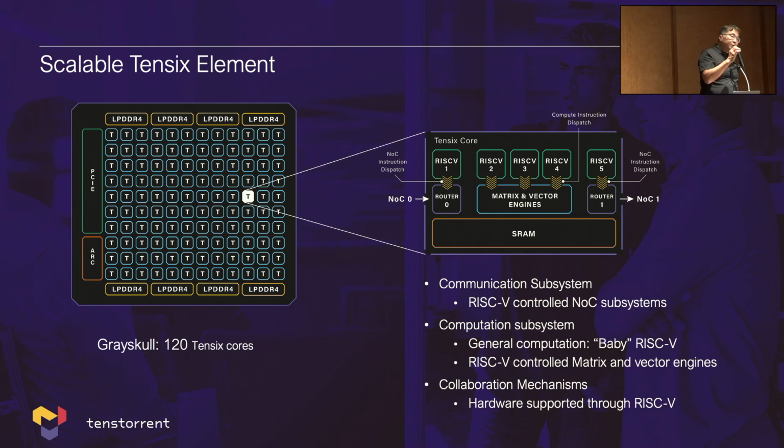Each of the processors here is very, very simple, because we're going to use them a lot. I will give you an example of the scale, how many cores are in there. And this system has a special function. They don't need to be super complex. The important thing is that they support the existing software stack. And also they drive very wide data computation. So they are not performing complex integer operations, but they are performing wide vector operations while maintaining some kind of programmability through the RISC-V architecture.